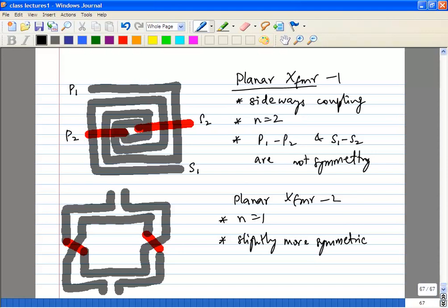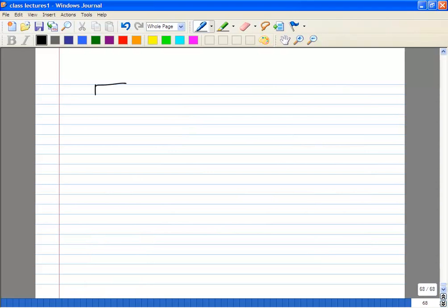If you look at the side view, you'll have very good magnetic coupling here, right? But as you go farther away, with current flowing on the other ends of the inductor, you'll have lower K, right? So there is a certain maximum you can get. It's typically around 0.8, 0.85.